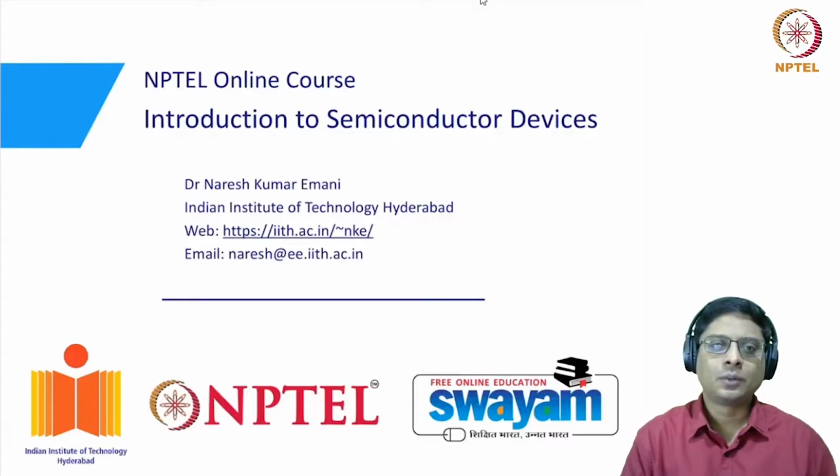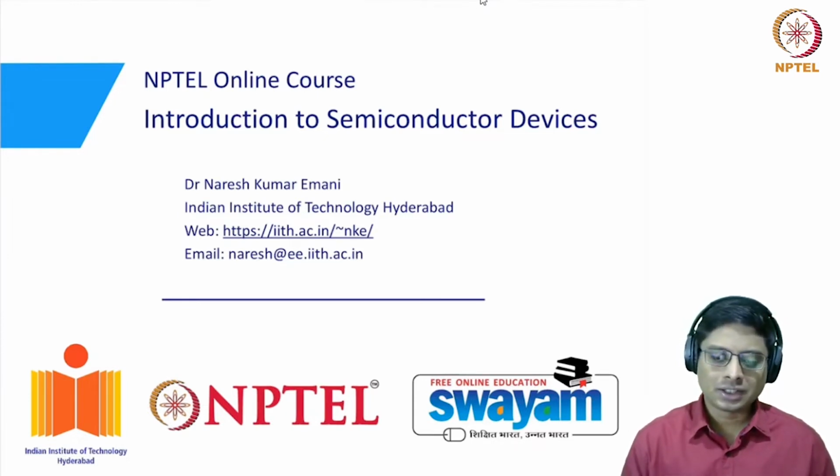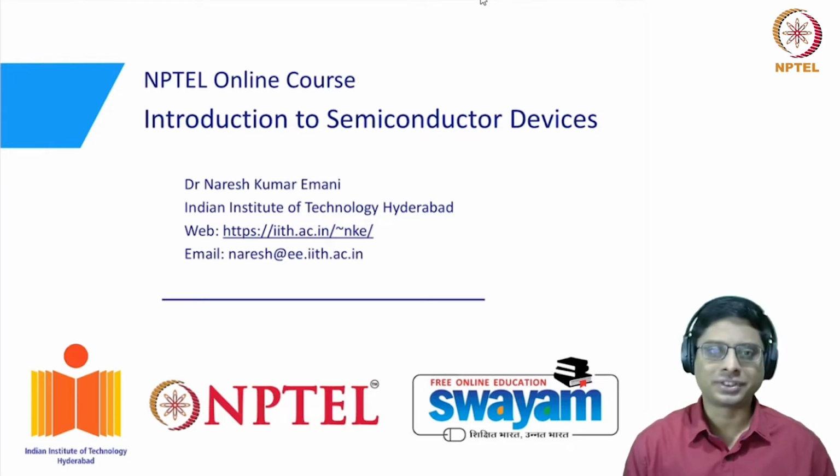Hello everyone, welcome back to Introduction to Semiconductor Devices. In the last week, we studied the basics of operation of a MOSFET. We looked at the saturation, the linear and the subthreshold regimes of operation. And then we have also derived some basic expressions for current as a function of gate and drain voltages.